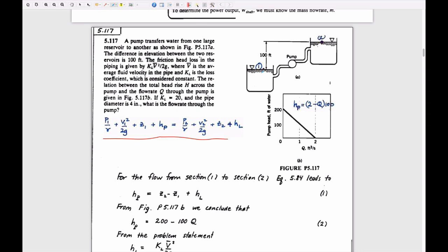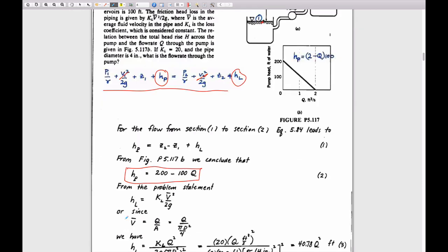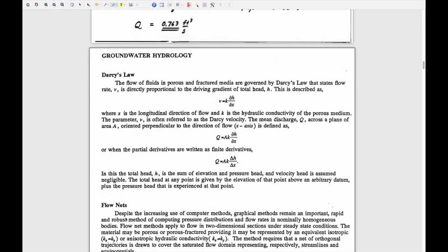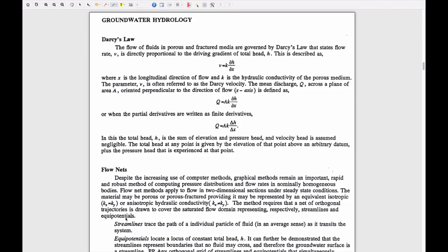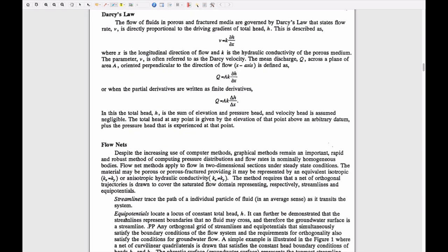So this is just writing Bernoulli's equation. Big tank assumption, you all know that, right? Big tank assumption, so you can get rid of these velocities. You can define the losses within the pipe in some way. You can define the pump equation in some way, here defined as a function of flow rate, and solve for the remainders. We went through that, so I'm not sure we have to do that again. This is an important part of what you may do in your lives, but it might not be an important part in this exam. You can take that for whatever it is worth.